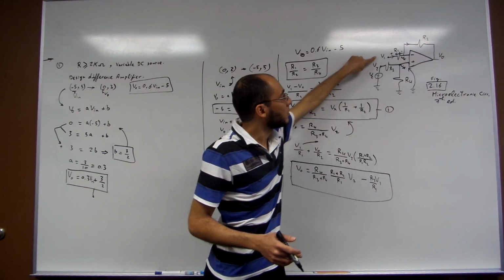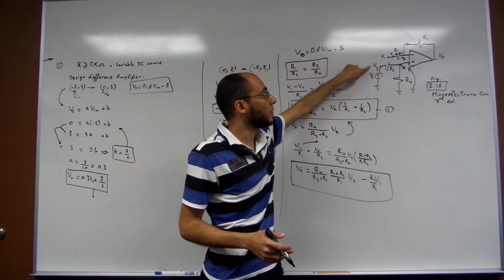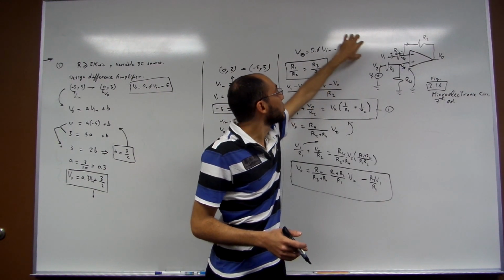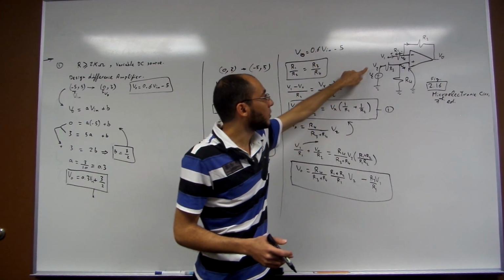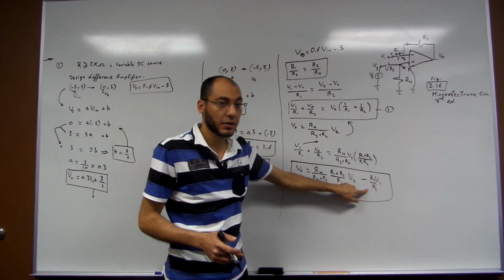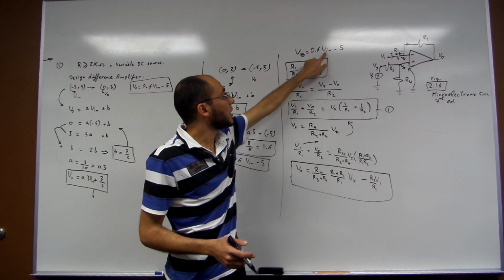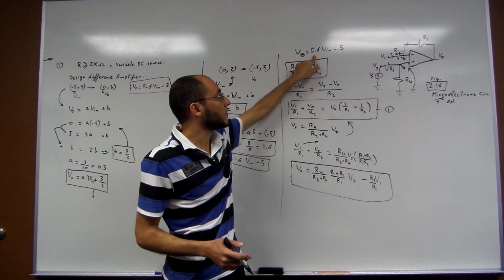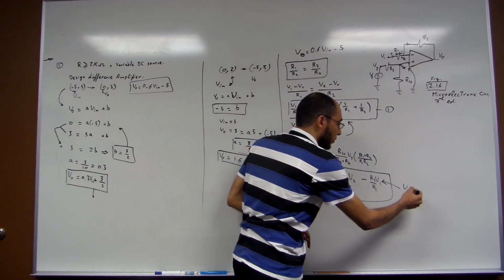If you look here, these are the voltages, V1 and V2. I want to put something in V2, something else in V1, in order to implement this equation. As you can see, V2 here is multiplied by a positive number, while V1 is multiplied by a negative number. And my duty here is to let V in be multiplied by a positive number. So obviously, I cannot choose V1 to be V input.